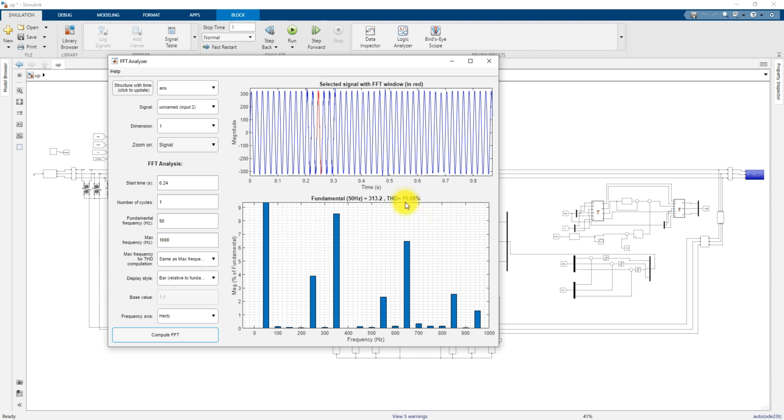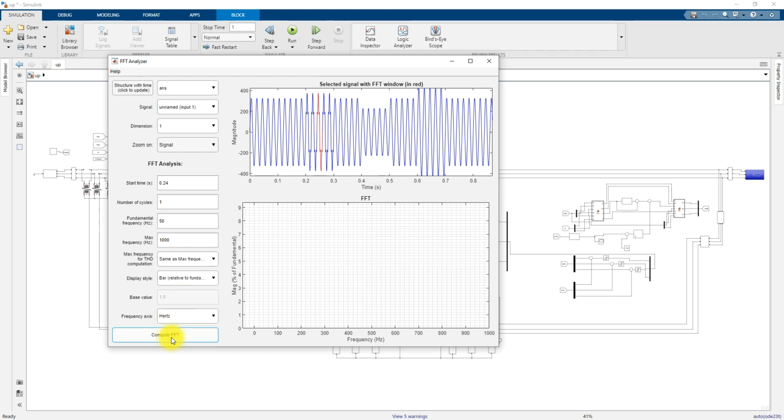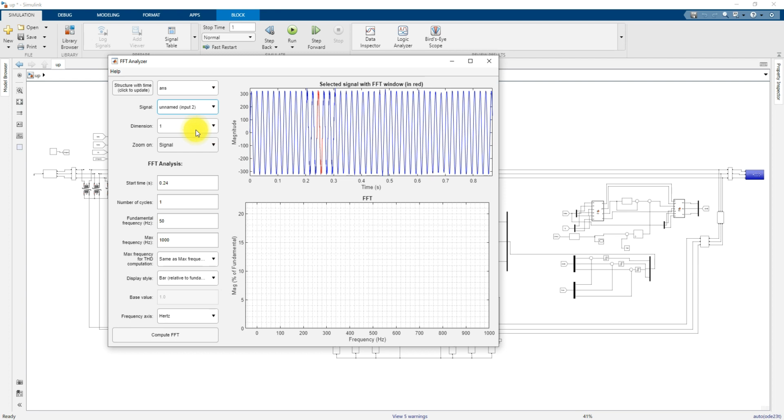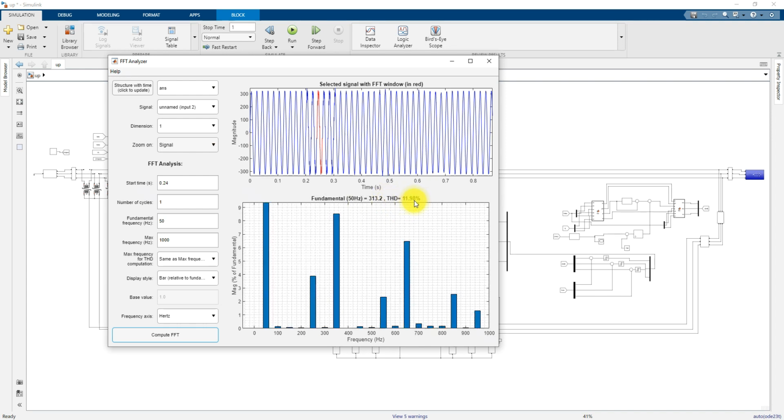So here we are getting around 11.98 percentage for source, so 20.62 percentage, right? During harmonics, the source voltage has a THD of around 20.62 percentage. After mitigation by using the UPQC by means of the DQ0 and PQ control theory, we are getting around 1.98 percentage. Okay, so it is reduced by around 9 percentage of THD by using this UPQC concept.